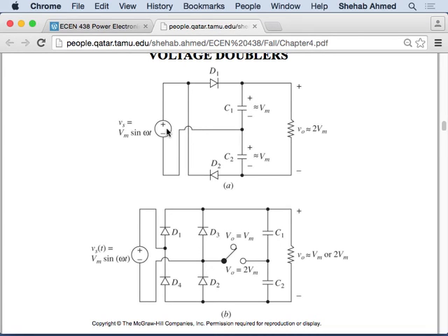So this capacitor voltage will be higher than the source voltage. Same thing as the rectifier. And this diode will stop conducting right beyond the V peak. Right beyond the V peak, the same story we had before: capacitor voltage will be maintained, supply voltage is going down. I've blocked D1 from conducting, but I've maintained the voltage across this capacitor.